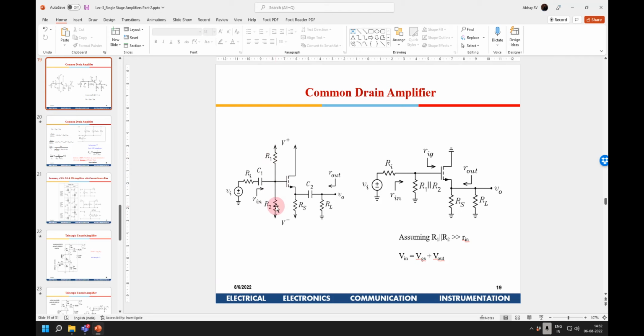No. This is individually when we talk about common drain. Correct. But when we're talking about the two stages, we don't need this setup, right? Correct. That is why we removed it. Already we showed the simulation, right? We removed those connections because the output DC level is not necessarily matching the DC requirement here. Correct?